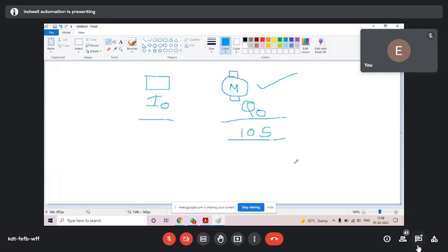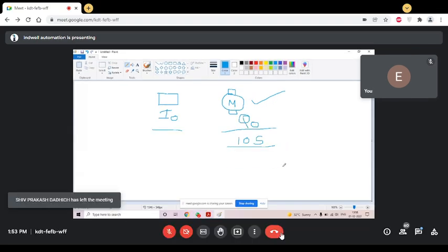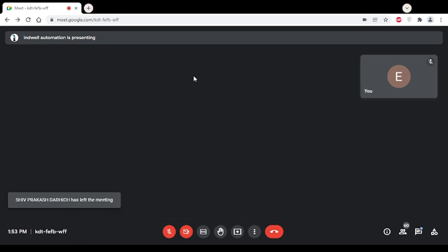Very good, Jose. But your program will run for one cycle only. Very good. You have tried well. Nice. Very good, Ganesh. Ganesh, we cannot have two coils in one ladder. After the coil, your ladder is finished, you go to the next ladder.